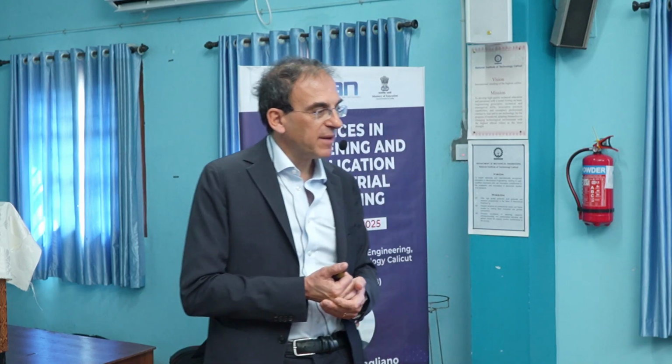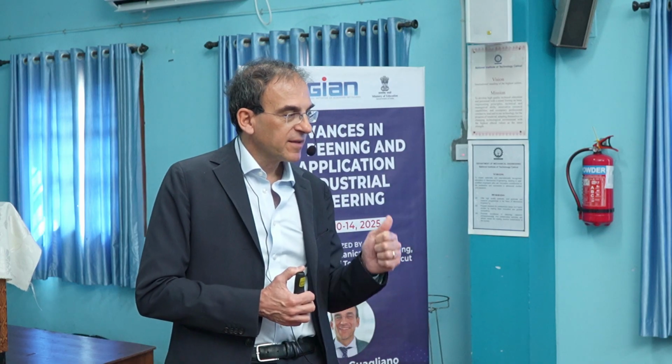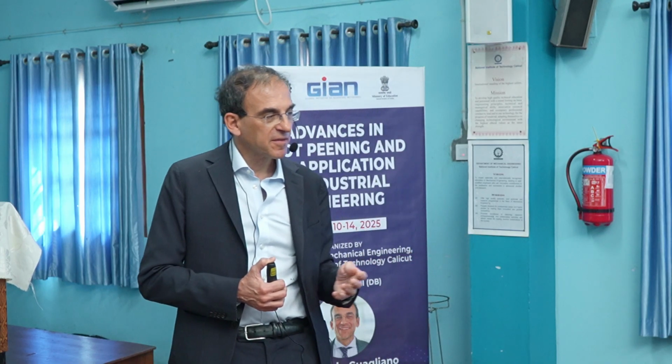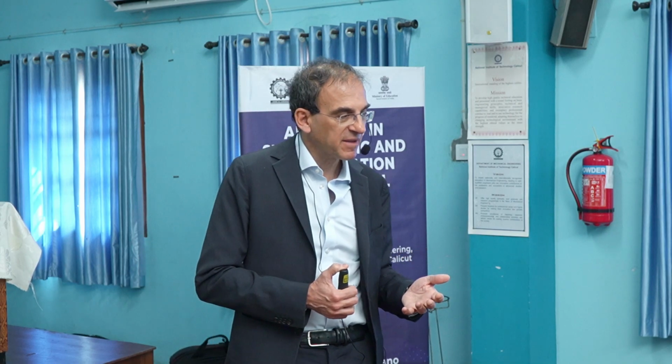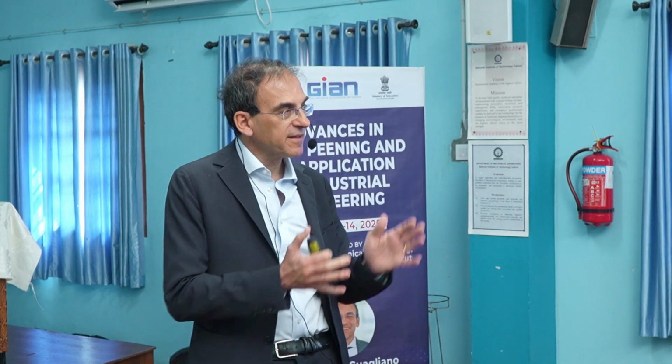It's important to see that the number of blades influences the projection of the shot. You can see here the difference between a wheel with one disc and 4 blades, 6 blades or 8 blades. And you see that the projection, the area that is of interest for the shot peening flow, is going to be narrow if you are using more blades. So what does it mean? It means that if you are using more blades, the effect will be more accurate.